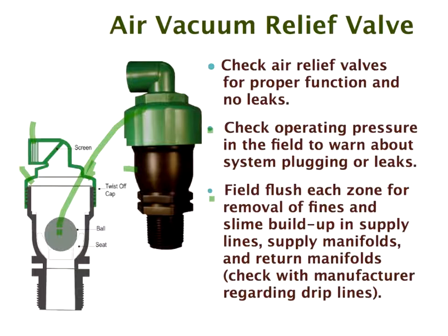Rodney, there's a question from Kemper. How does the valve release the vacuum? Okay, here's the ball. You see the ball there. Under pressure it gets pushed up and the air gets pumped out. Then when you switch off, it comes back down, and there is a relief slit in the valve, which you actually can't see in the seat, that allows the air to come back around there and back down here.